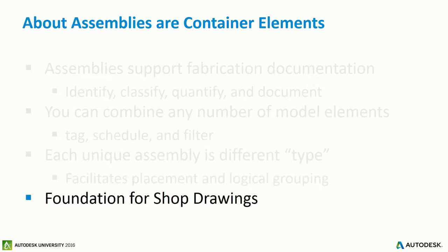It also creates the foundation for shop drawings. So shop drawings are created in Revit from an assembly. So with no assembly, no shop drawings. You could create your shop drawings by creating a view that filters out everything from the view other than the things that you know are part of that assembly. You can create that view, you can put it on a ticket. You can manually do this process, but the assemblies allow us to group these things in a logical sort of way.